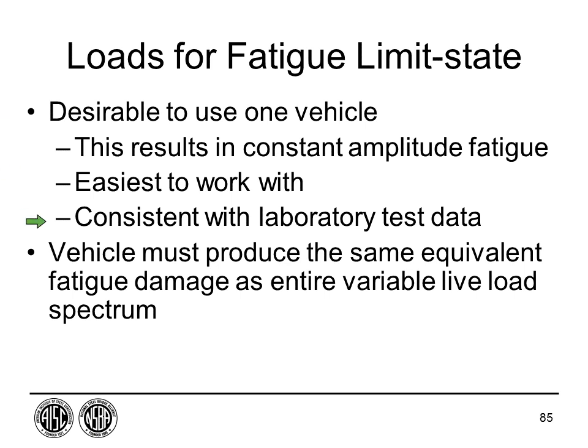And if you recall, the fatigue tests in the laboratory are constant amplitude. We apply a single stress range, so it would be nice to use a single truck because then I have a single stress range. But again, it's important. This truck has to give me the same fatigue damage as that entire spectrum of different trucks of different weights and positions.